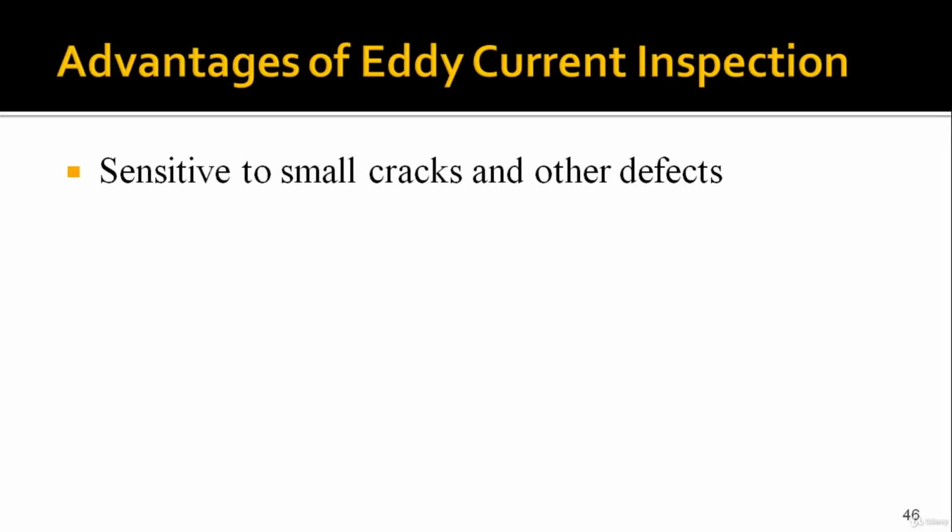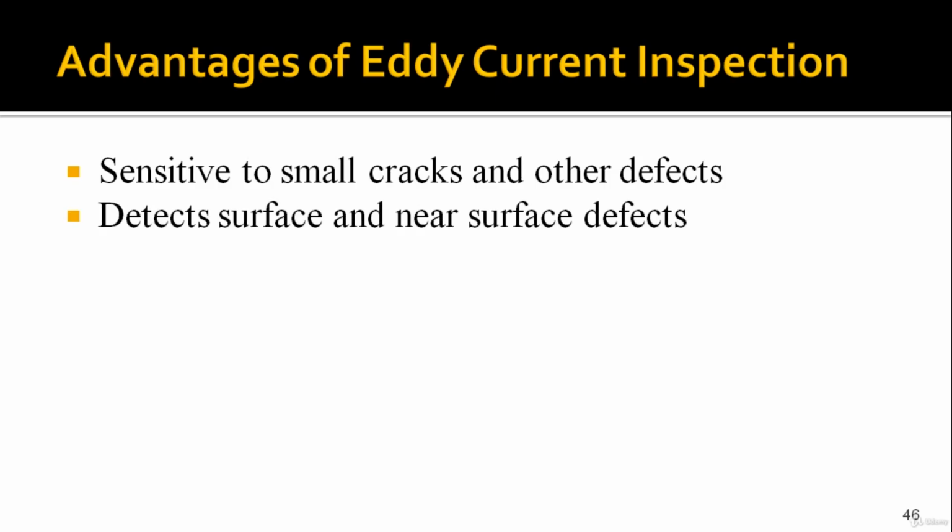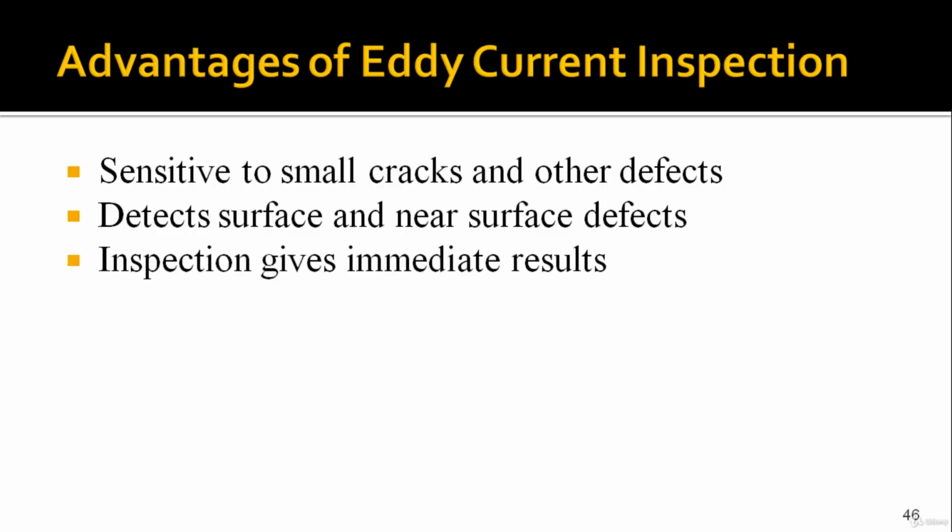The first and foremost advantage is that it is very sensitive to small defects. If there is a small crack or defect, it can be detected by eddy current. It can detect surface and near surface defects. In visual testing or dye penetration testing we cannot detect subsurface defects, but here you can also see the subsurface defect up to a certain level.